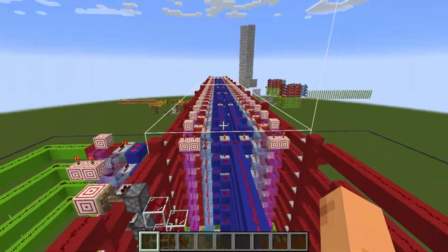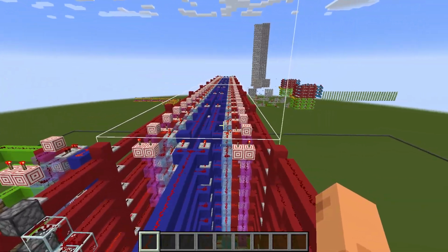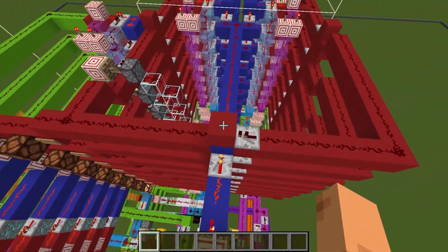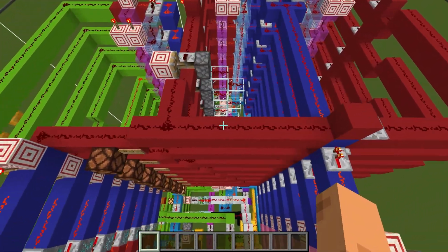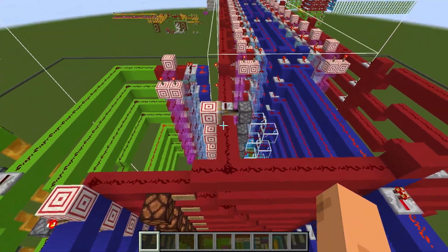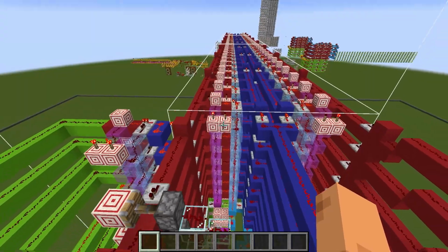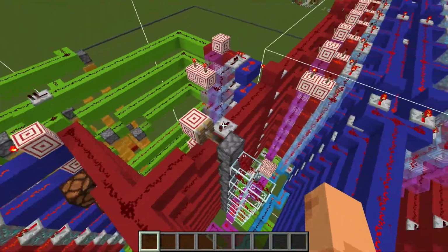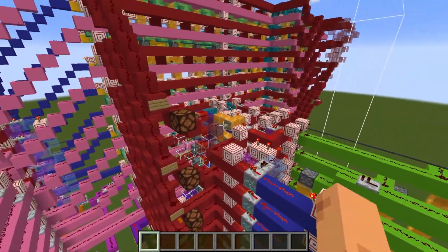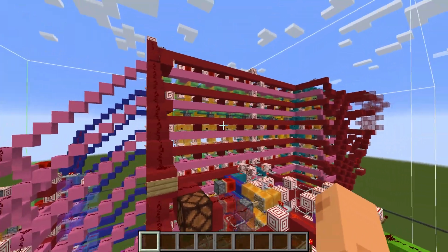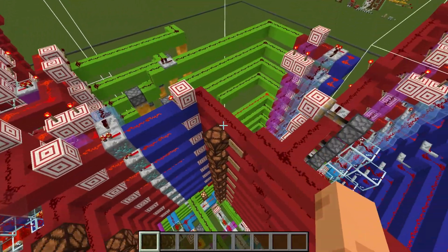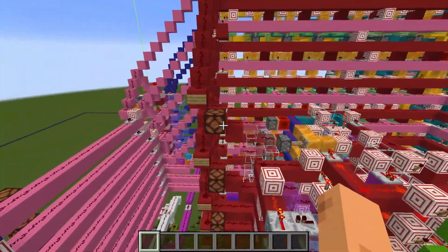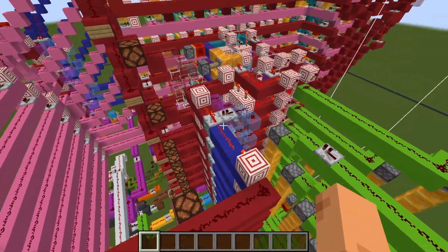Remember I said that we read both sides of this memory controller, but we only get one value when we merge them right here at this junction. But that means that when we have both values available, we can switch between them very quickly. And so when we get the opcode, we can buffer it or let it pass through into the ALU and then switch to the other side of it and get the data value to do the next operation immediately.